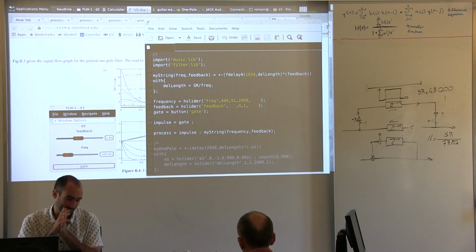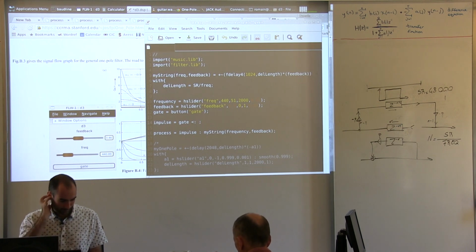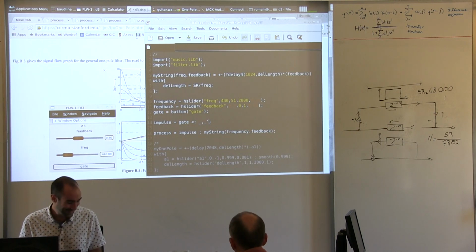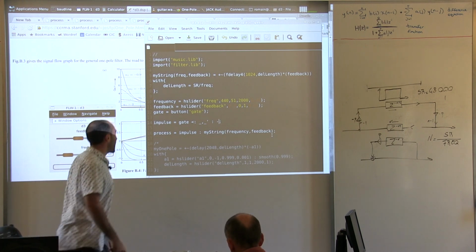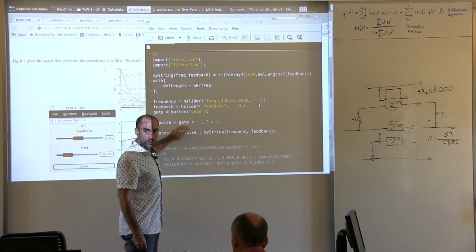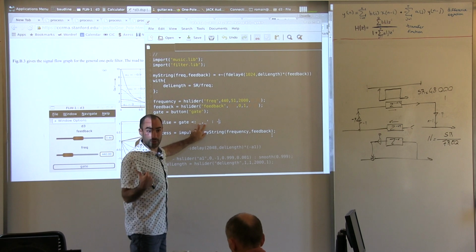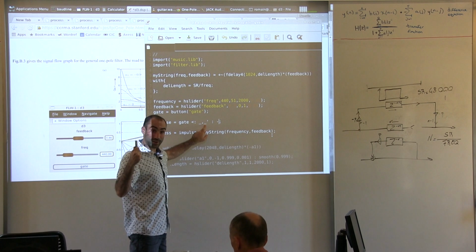Very good. So what I'm going to do is that I'm going to split the signal of the button into two signals. One, two, and one of them I'm going to delay it by one sample. And then I'm going to subtract them together. Okay? So now what happens is that when I press the button, so when the button is pressed, I go from 0 to 1, okay? So here I have 1, but the previous sample I had 0. So 1 minus 0 equals 1. Good.